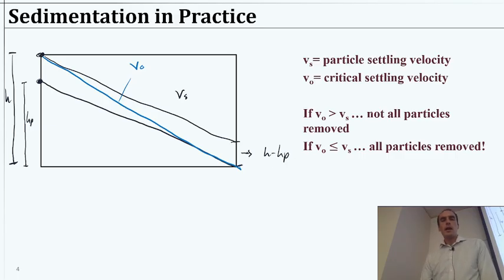So imagine, again, the bowling ball if you have any confusion. Compare the bowling ball particle to a slower particle. If you design a swimming pool such that it should remove certain particles with some flow going through it, well, that's kind of overkill for a bowling ball. Bowling ball will hit the ground in a very short amount of time. So you could be flowing a lot of water through there and still settle out that bowling ball. So keep that in mind.